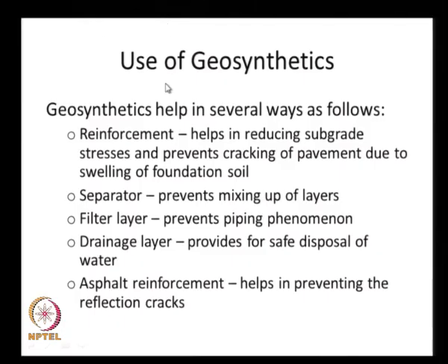Let us now look at how we can use the geosynthetics in the case of flexible pavements. The geosynthetics we can use in several ways. One is as a reinforcement layer. If we use a very stiff and strong reinforcement layer, it can help in reducing the subgrade deformation and prevents the cracking of pavement due to swelling of the foundation soil.